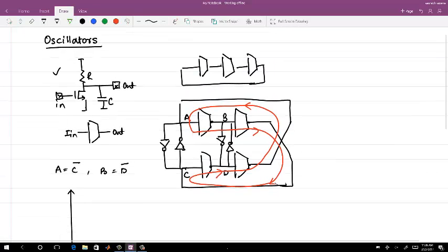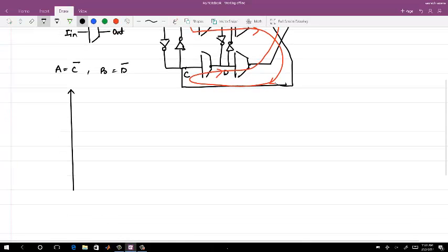If the gain of each cell is A naught by (1 plus s by omega p), this is the gain of each cell. So this gain will be minus 180 degrees, not minus 180. You have A naught to the power 4, and then this will go down as minus 80 dB per decade, the loop gain.